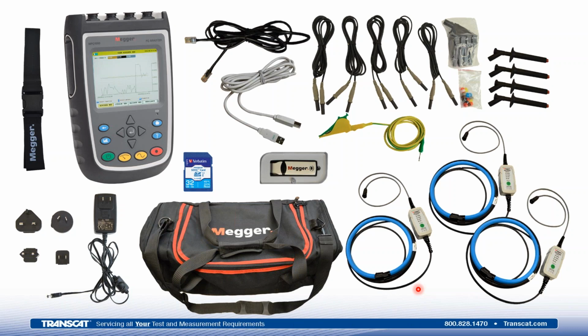These CTs here are 4-range CTs as well, so you don't have to carry a bunch of CTs. I would suggest that. Also, having some small plunger clips so that you can get to the harder to reach places to hook your voltage leads up to. And also a 32 gig SD card so that you can have long recordings for over a year if necessary.